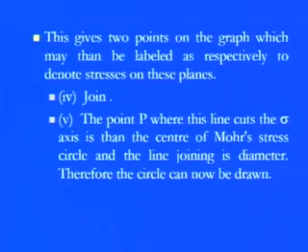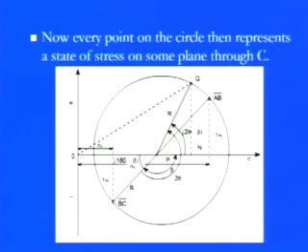First, whatever the cutting part is, the extreme end point on the top of the surface gives you the center of the Mohr circle. Whatever the location of the point P is, this gives you the center point of the Mohr circle, and the line joining, if it is just passing through these, will give you the diameter. So the circle can now be easily drawn using all the information we discussed here. So now you see here this is the Mohr circle.